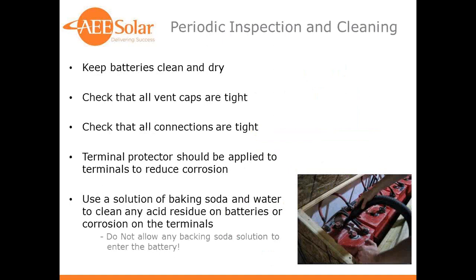Periodic inspections and cleaning of the batteries is very important. Batteries need to be kept clean. Tops of the batteries should be wiped down with a rag or a cloth and a baking soda solution to keep them clean. If you have too much electrolyte buildup on the top of the batteries, it can form electrical paths that can cause short circuits and also obviously corrode wire connections and whatnot.